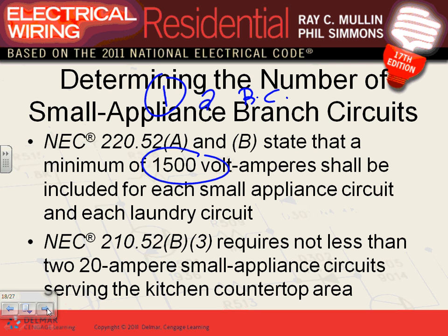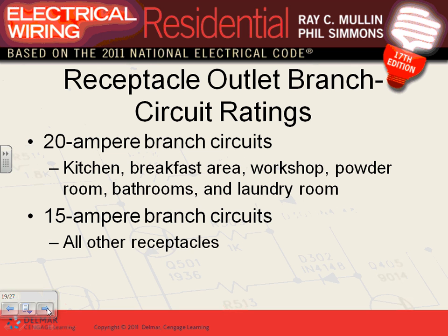And when you do your calculation, remember Chad's 9,000 volt-amps that we just calculated? You're going to add the 1,500, multiply it by 2, and add it to the 3,000 that Chad just calculated for his house. Questions? You have no other options. You have to put two 20 amp circuits. So that's it, 20 amp circuits for the kitchen. This is my 20 amp circuit.